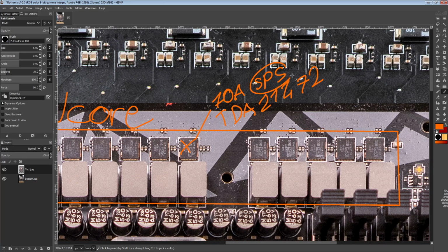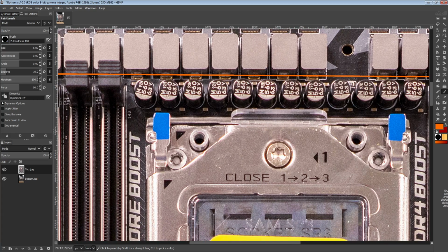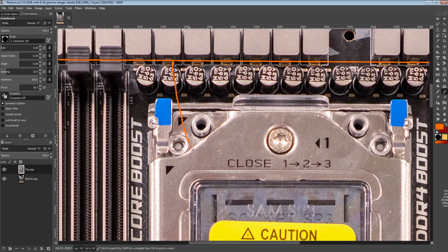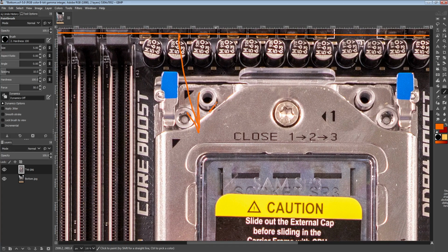So yeah, and these are called smart power stages because they integrate better current monitoring. They also integrate temperature monitoring, over temperature protection, over current protection, and a bunch of other protection features that I don't really care about remembering. So anyway, the end result of these lovely power stages is that the VRM has the following efficiency.